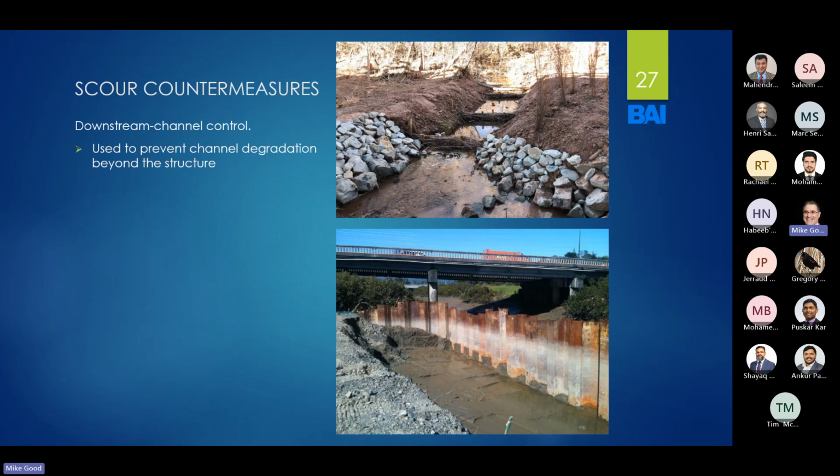I believe we did that. I'm trying to remember what the project was. It was before I came on to Brutus, but there is a project that we use frequently to show our hydraulic analysis capabilities and our stream embankment improvement capabilities, and we used riprap lined all the way up and down the channel to protect against scour.